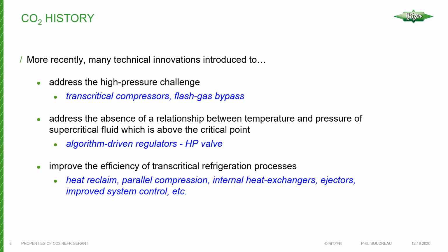Okay, so what I mean by that is when the refrigerant's above the critical point, you can't take your temperature pressure chart, look up a pressure and find out what saturation temperature is, because there's absolutely no relationship between pressure and temperature when we get above the critical point. So in this case, the high pressure valve, some people call them the magic valve.